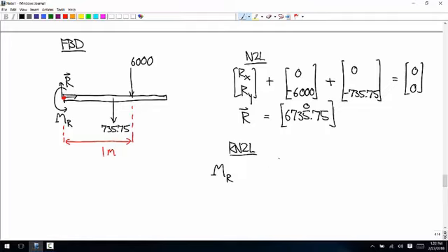Okay, so I'm going to write this all in here. The moment arm, that's acting right at the midpoint of that beam, so the moment arm is going to be 0.75. The force is 735.75. I just wrote both of those as positive. And now we'll think about the direction of the rotation that that produces.